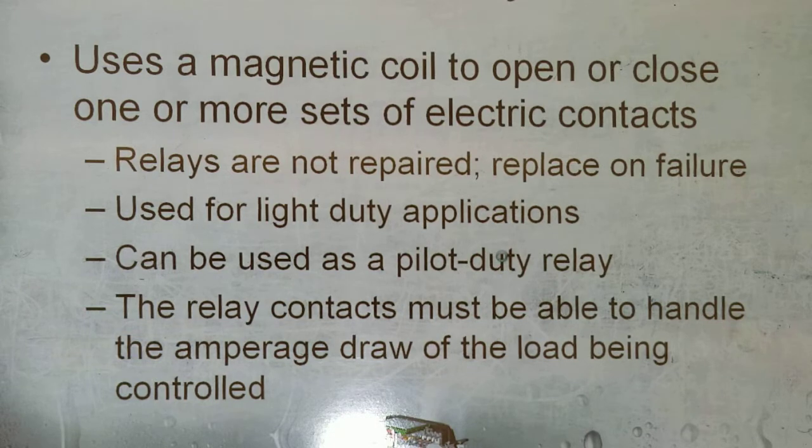The relay uses a magnetic coil or coils to operate one or more sets of electric contacts. Relays are not required to be replaced on failure. Used for light duty applications, they can be used as a pilot duty relay. The relay contacts must be able to handle the amperage draw of the load being controlled.